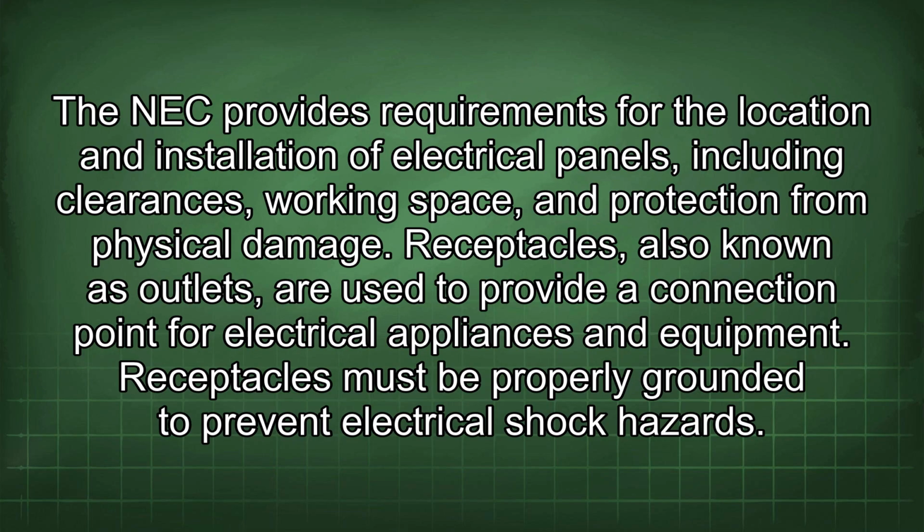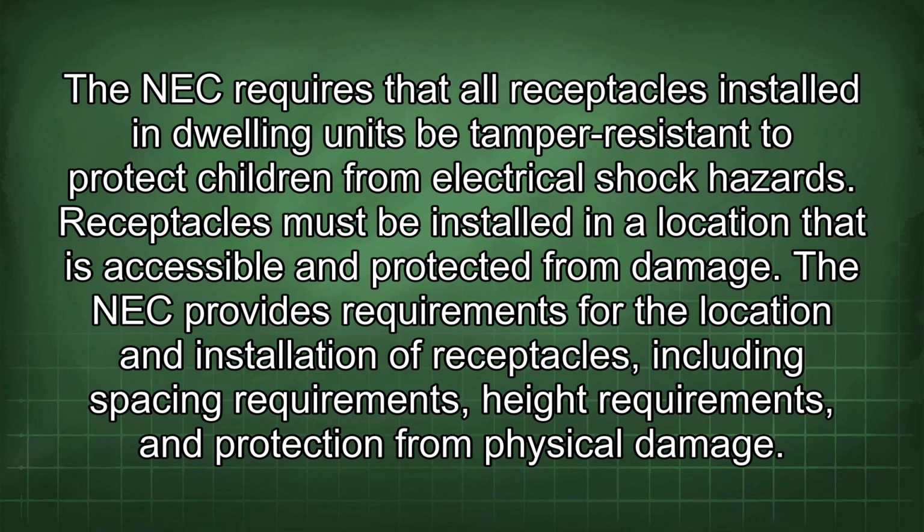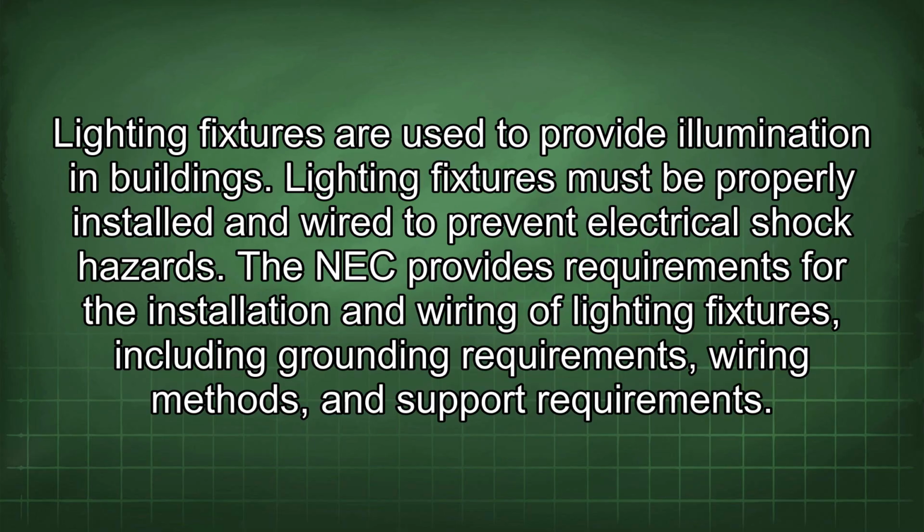Receptacles, also known as outlets, are used to provide a connection point for electrical appliances and equipment. Receptacles must be properly grounded to prevent electrical shock hazards. The NEC requires that all receptacles installed in dwelling units be tamper-resistant to protect children from electrical shock hazards. Receptacles must be installed in a location that is accessible and protected from damage. The NEC provides requirements for the location and installation of receptacles, including spacing requirements, height requirements, and protection from physical damage.